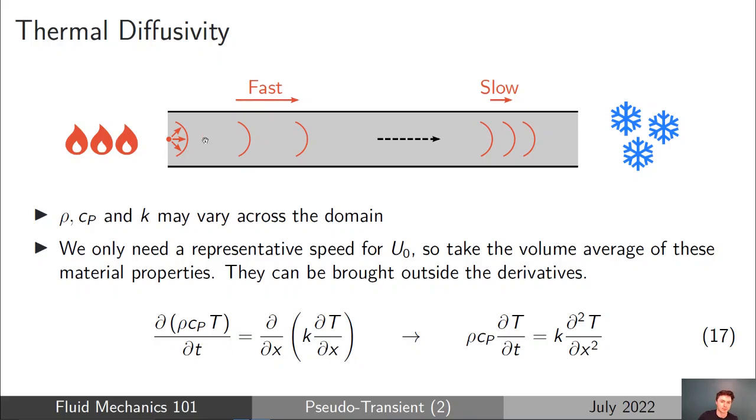It may be a solid with properties that vary, and so, of course, that means that with this 1D heat conduction equation, the speed that that boundary effect propagates can actually vary through our solid domain, depending on how we had it set up. And of course, areas with lower specific heat capacity would heat up really, really fast and have faster propagation speeds, whereas areas where the specific heat capacity were really high would take a lot longer for that boundary effect to propagate from the left end of the bar to the right end.